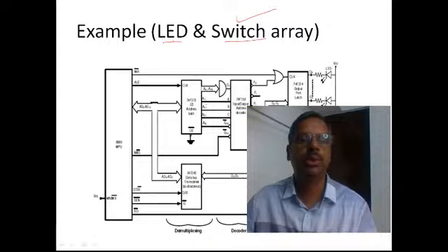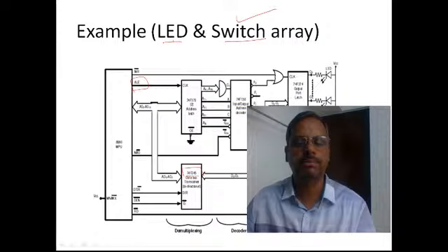The clock input is triggered from the ALE of the processor, which we have already discussed. So we demultiplexed higher order address lines with this, and then we demultiplex lower order data lines through this 74245.